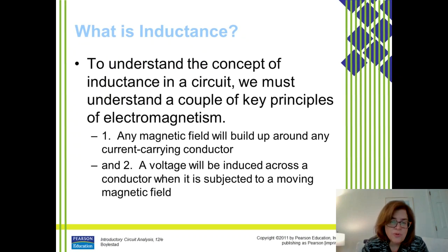The other principle that you need to know is that when we have a moving magnetic field, for instance, if we're growing a magnetic field or if we're turning a magnetic field, it will induce a voltage. And actually, it'll be counter, in the opposite direction of the voltage that created that field in the first place. So those are the two principles that we're going to apply when we talk about inductance, because it helps to understand what that inductor is doing.